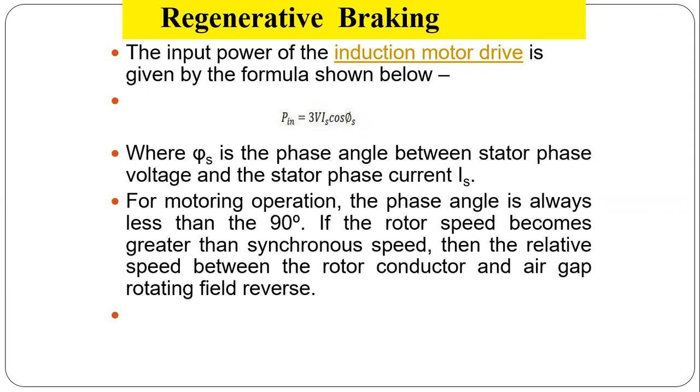If the rotor speed becomes greater than the synchronous speed, then the relative speed between the rotor conductor and the air gap rotating field will be reversed. The main point is how to create and develop regenerative braking in the induction motor drive.